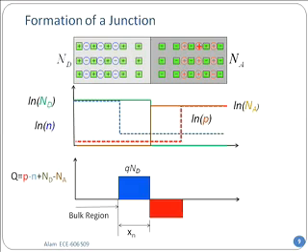One thing you realize is that the area under the blue and the area under the red have to be the same, because of the charge balance. If they were not the same, there would be a net electric field coming out of this region. If you apply Gauss's law and take slices, if these two pieces were not the same, it will adjust until they become the same. Until it becomes the same, it will not stop. So this is a very important statement: even when you have a non-uniform device, at the end the whole sample as a whole is charge neutral. And that's the statement. The area under the blue and the area under the red are exactly the same.